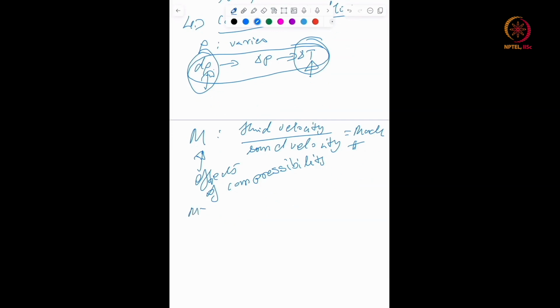When Mach number is greater than 1, the flow is called supersonic. That means dramatic and sudden changes in fluid velocity and thermodynamic properties. You get things like shock waves, across which the pressure varies quite a bit, and these shock waves are irreversible and non-isentropic.